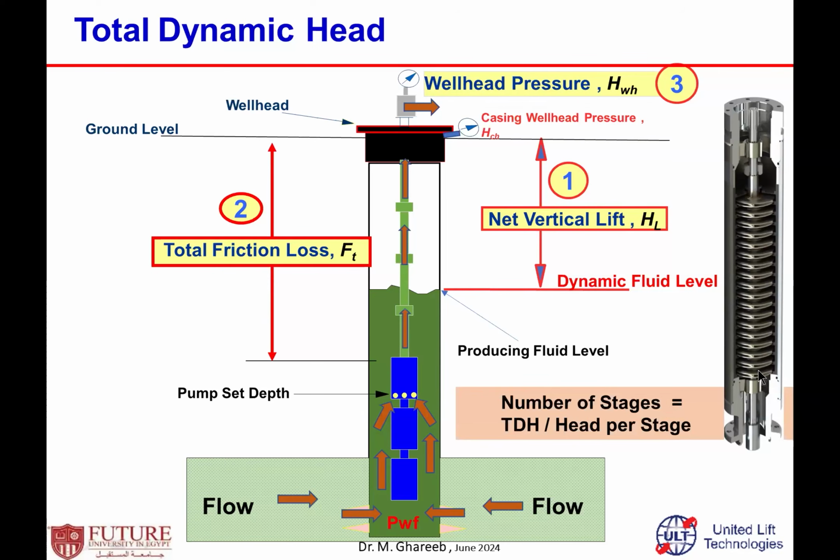Remember the pump performance curve we presented in the previous slides. For each one stage, how much total dynamic head does it generate? Based on the total dynamic head I have, divided by the head per stage, I can calculate the minimum number of stages I can use for this type of well, or to produce these wells, and so on.